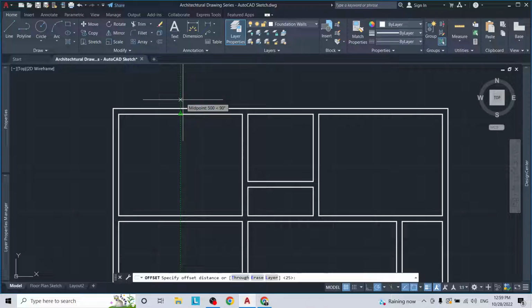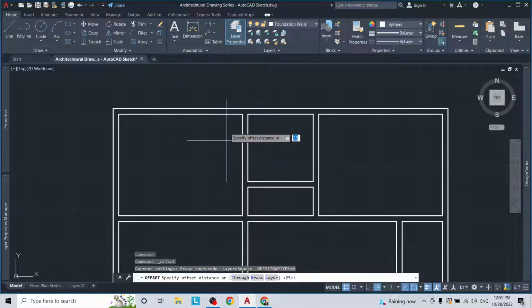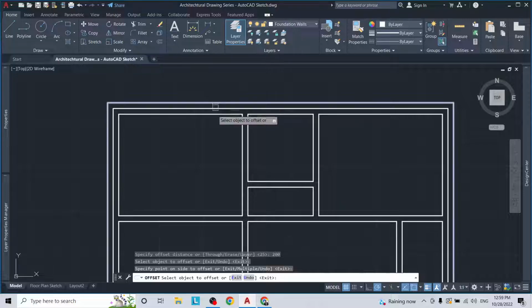I believe it's right. It's 400. We're gonna offset the remaining 400 evenly, equally on both sides of the wall, so that the wall would sit directly in the center of the footing. So I use the offset tool, and then I'm going to use 200 as my distance. So I offset 200 on that side and then 200 on the inside, like so.